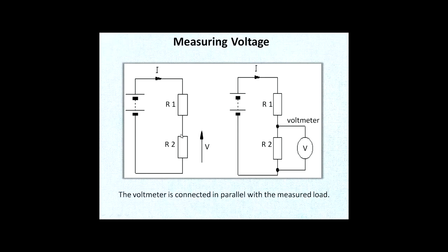What's the highest resistance? Okay, over here we have also high resistance across this resistor and high resistance across that resistor. It's the resistance of air, okay? It's extremely high. Now, we also want to have extremely high resistance of the voltmeter. So if the resistance is extremely high, then the current flowing through this voltmeter is going to be extremely low. So we're taking a tiny, tiny bit of a sample of the current, and it's so tiny that it's insignificant to the whole circuit. It's not really affecting the circuit here.